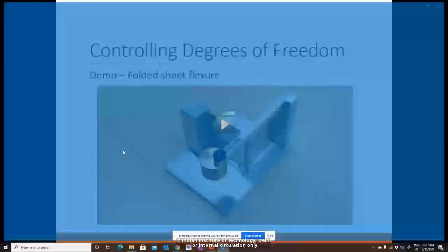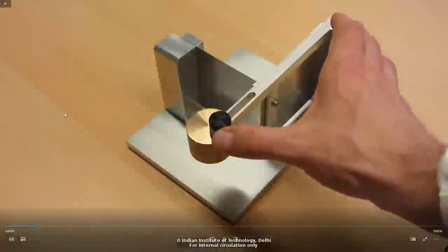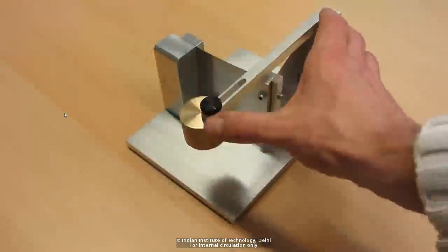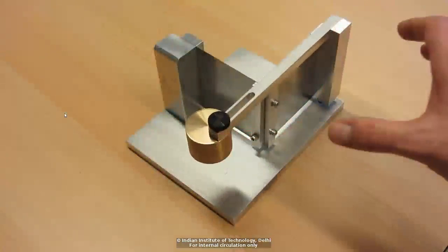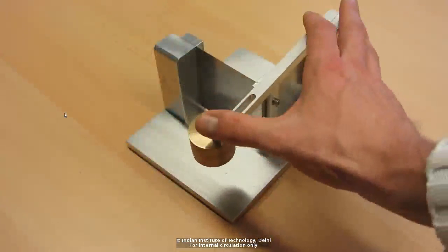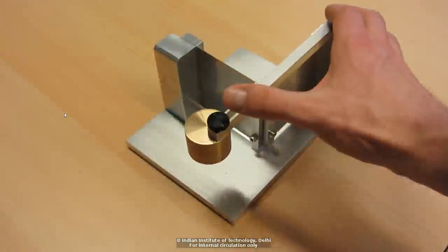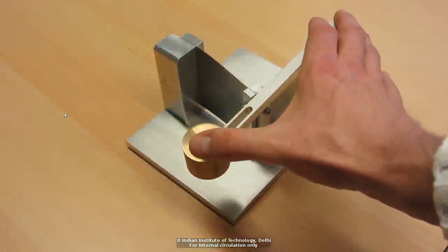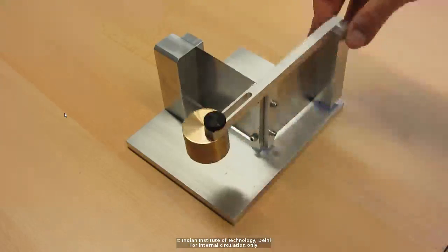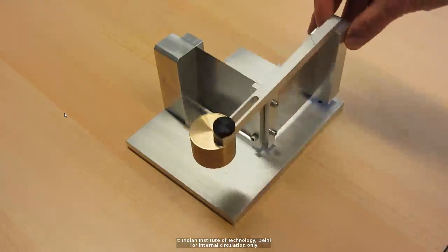So you see this video. What you see here is 2 leaf springs connected together, and then at the end you have this, showing different motions. The rotation, okay, it can rotate very easily, so it's a compliant direction again. Yeah, you can simply translate also. Twisting is possible.